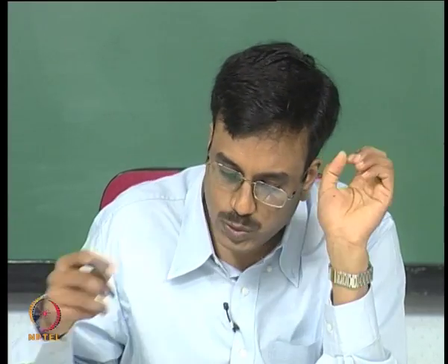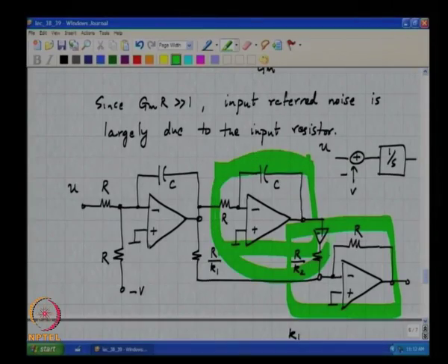So, since we know that the noise of subsequent integrators does not really matter, because when referred to the input of the modulator they get divided down by the high gain of the first integrator in the signal band, it is acceptable to make them deliberately noisy, right, and gain in the form of power dissipation.